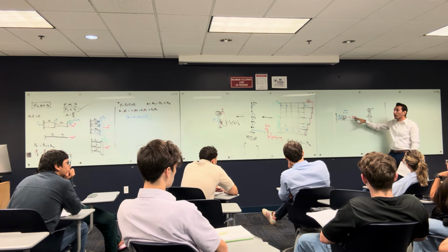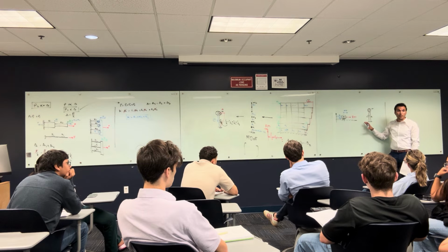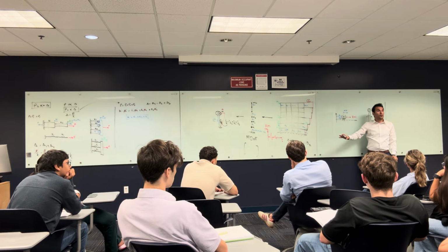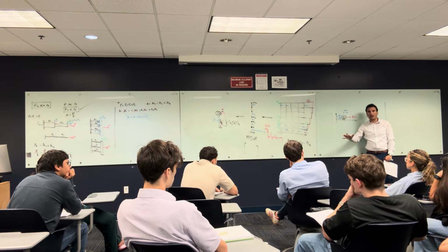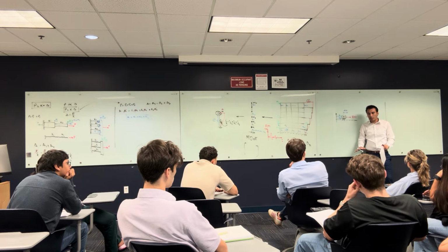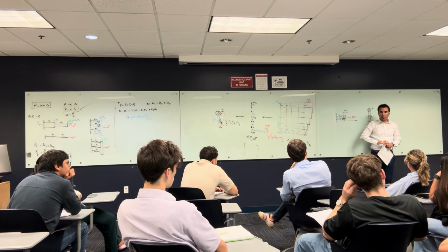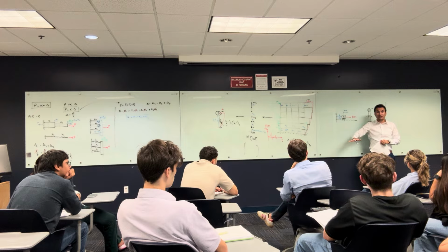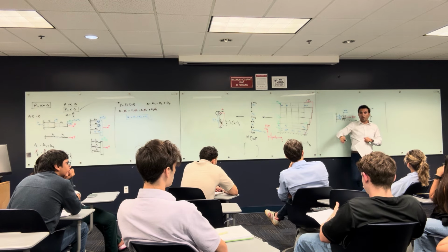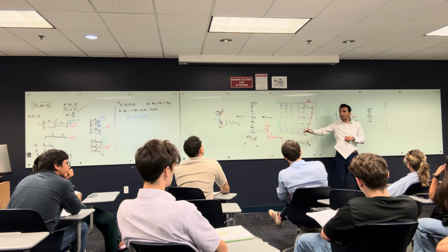So Ft is a function of the earthquake itself. Maybe all the structures in the same zone are exposed to the same ground acceleration. However, this is not exactly true, because if you go away from the epicenter of the earthquake, this ground acceleration gets less. So the ground acceleration depends on where you are relative to the epicenter.